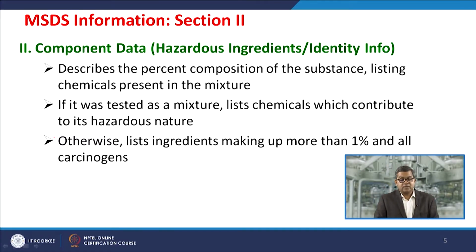Now this is extremely essential because suppose the component you are dealing with is say 50% pure, or it has a minimum assay of say 75%. That means the rest are other components. This may create a future problem in your reactor or in the reaction kinetics, etc. So you must know, because sometimes this may lead to the production of undesired components. So you must know this particular information so that prima facie you can take certain precautionary measures.